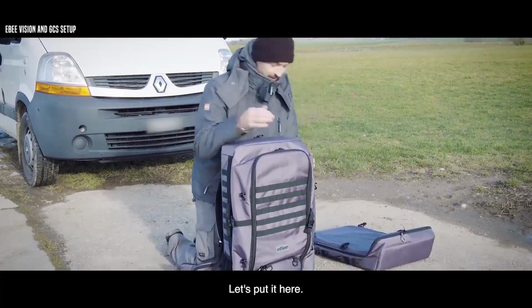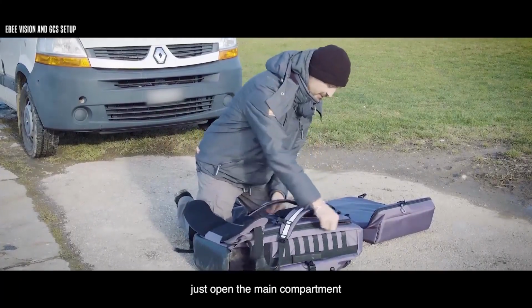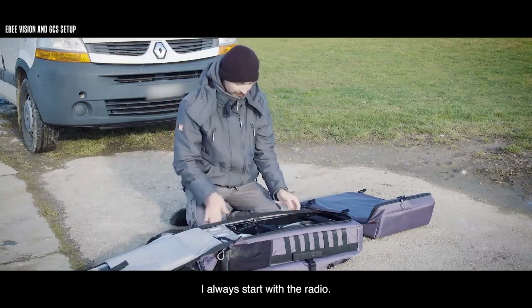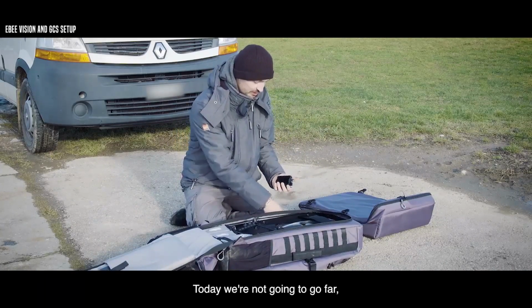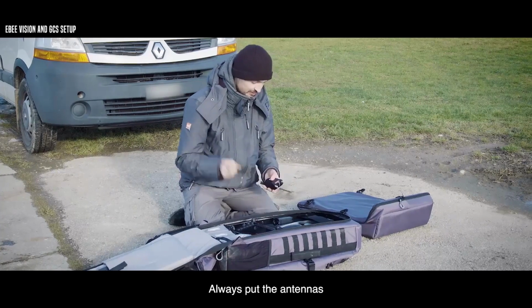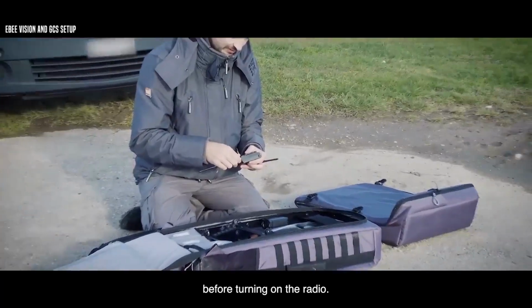Let's put them here, and now we just open the main compartment where the drone is. So I always start with the radio. So today we are not going to go far, so we'll go with a small range antennas. So always put the antennas before turning on the radio.